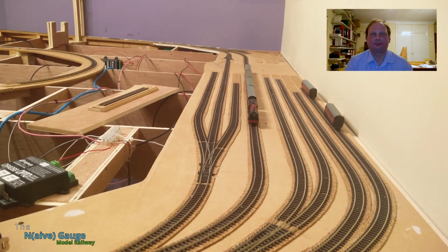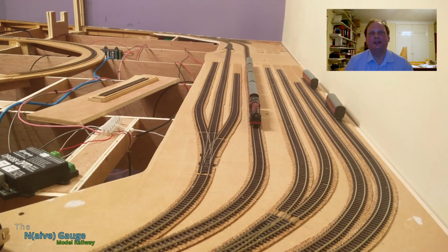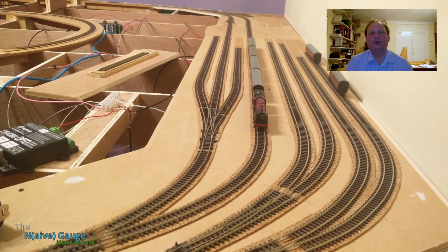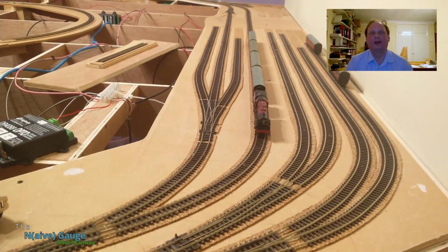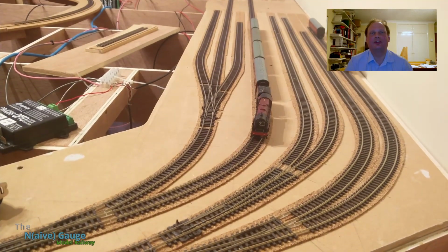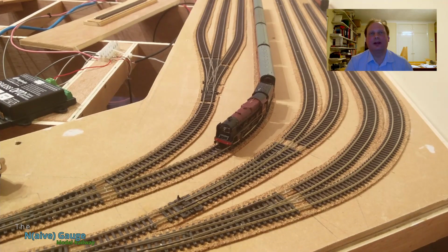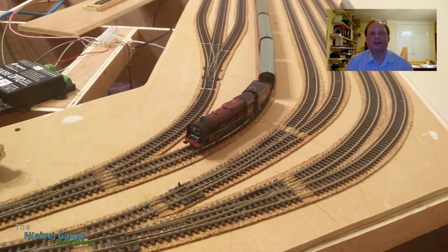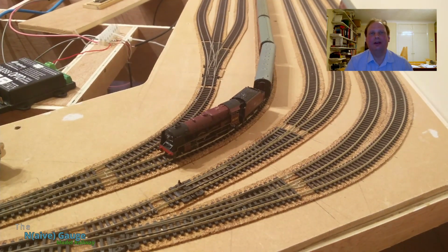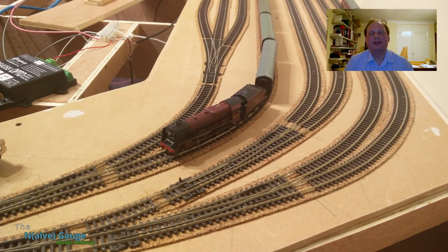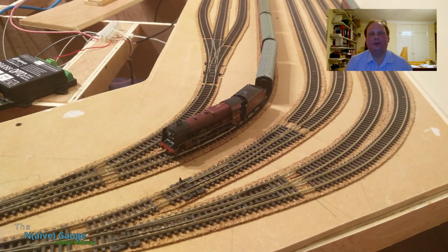Now the way in which it's working out where to stop within the block is it knows the time at which it entered the block and it knows how fast it's asked the train to go. And from that it's worked out exactly how long it's going to be until it asks it to stop. Now it's going to stop, there we go. It stopped quite near the end of the block. I configured it to try and stop it 10 centimeters away from the end.